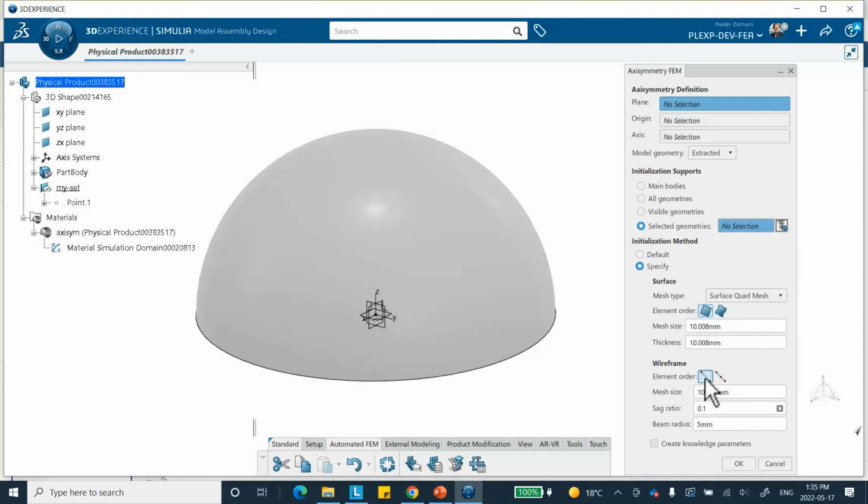Mesh, the axisymmetric shell. You can do the continuum one, or based on beams, you can create an axisymmetric shell. I don't want to do this in this tutorial. I'm just using this. So look at what it's asking. It's asking for the plane. So I have to choose a plane, which basically tells you where that axisymmetric profile is going to be. So I can use YZ or XZ, or I could have created another plane, doesn't matter. I will use YZ.